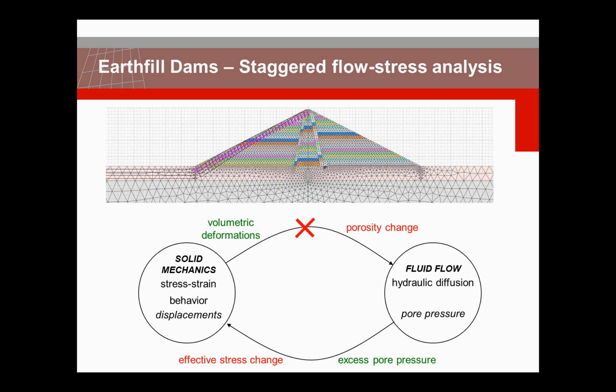So this is again a multi-physics approach, in which we first do a groundwater flow analysis, and the calculated pore pressures, the excess pore pressures, will be applied as a load to the dam body, and then we can calculate the stresses and displacements.